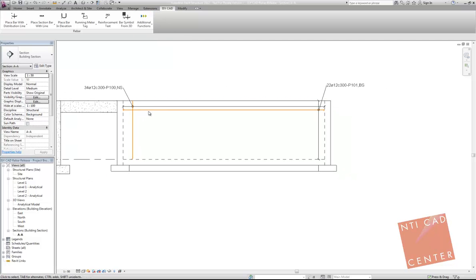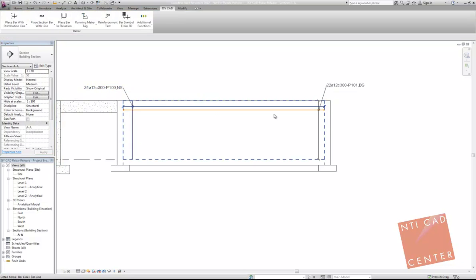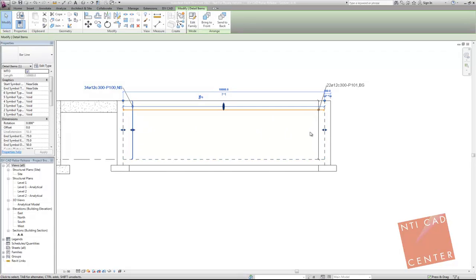So let's say we have drawn some rebar. This is being drawn so far as just 2D symbols. So basically, if I select this one, you see that this is a symbol of the rebar. I have some properties here, for example, offset, the one which you could use, for example, for cover settings, etc. Some other parameters. And for example, when I select this rebar, you see that I have these arrow grips. So basically, if I change this, you see the amount of the rebar is being changed.